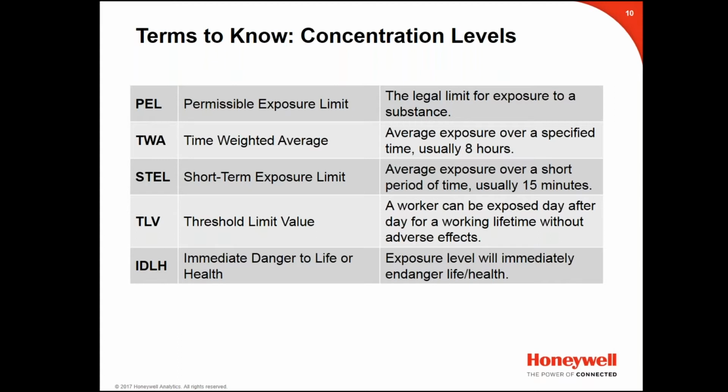Some toxic gases may have permissible exposure limits that are safe for shorter periods of exposure time. So you'll encounter short-term exposure limits, or STEL. These are also synonymous with ceiling limits, and this is generally for a 15-minute period of exposure.